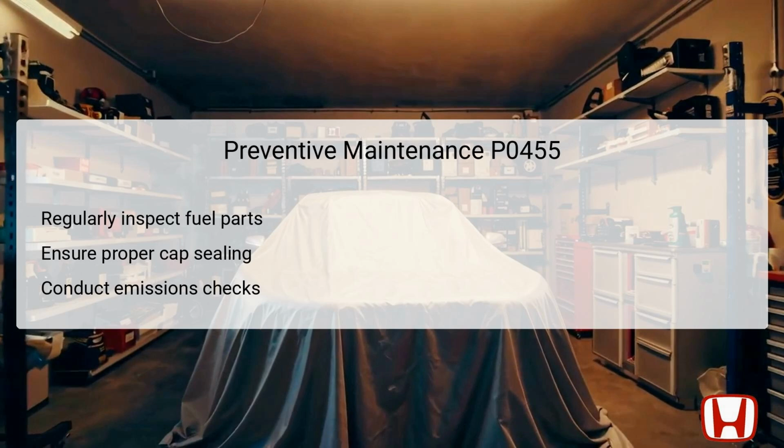Ensuring that the fuel fill cap seals properly can save on costly repairs down the line and maintain vehicle efficiency. Scheduling and conducting periodic emissions checks also provides an opportunity to detect any EVAP system issues early, allowing for timely interventions. These proactive steps promote not only optimal vehicle performance, but also contribute to environmental conservation. Adhering to routine maintenance practices can significantly reduce the likelihood of encountering similar DTC errors in the future.